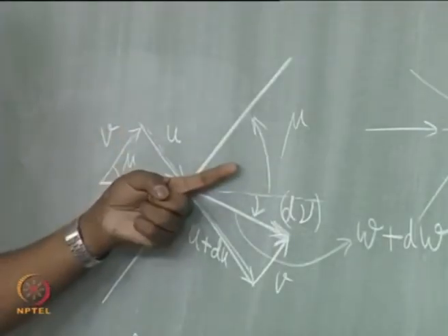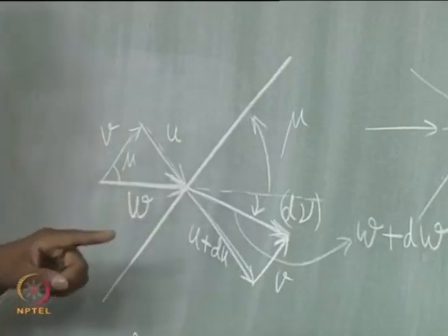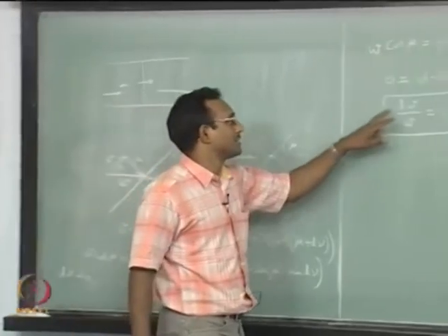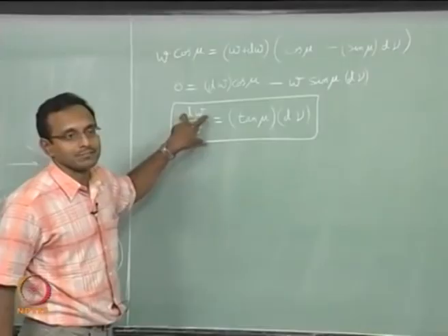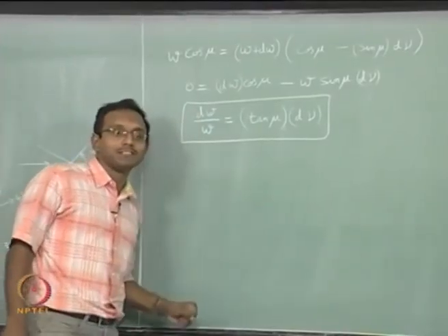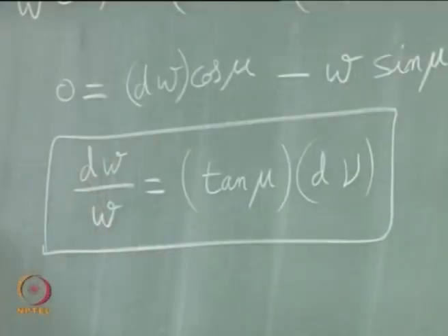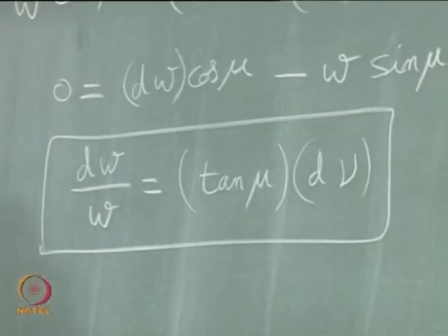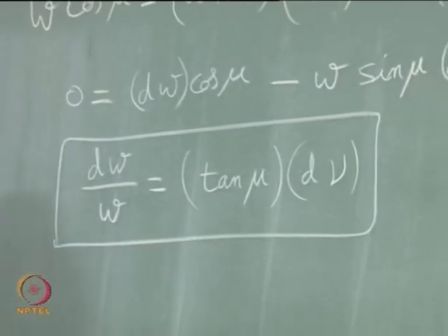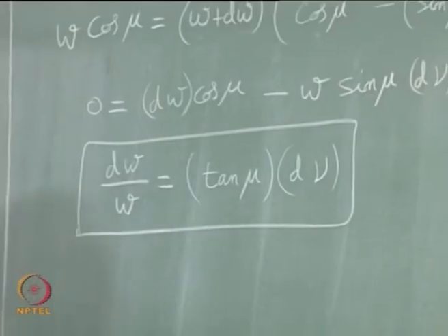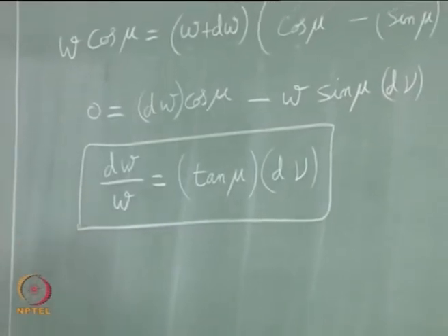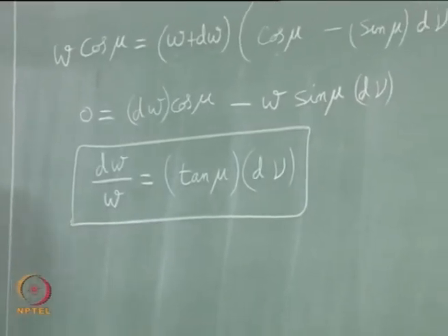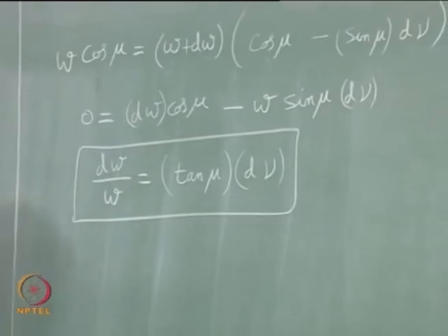The flow vector will go the other side. If that is the case, automatically this expression gives me dw is negative, which means my velocity decreases. Okay. That is what I am getting here, which means that will correspond to a Prandtl-Meyer compression wave, okay, a single compression wave we are talking about, almost isentropic but compression wave. That is the answer you will get from that.